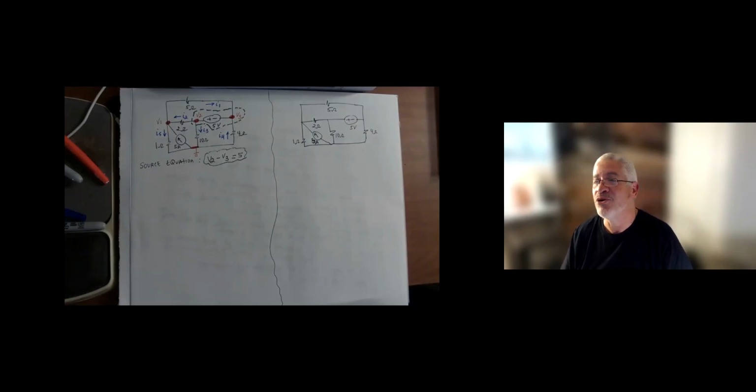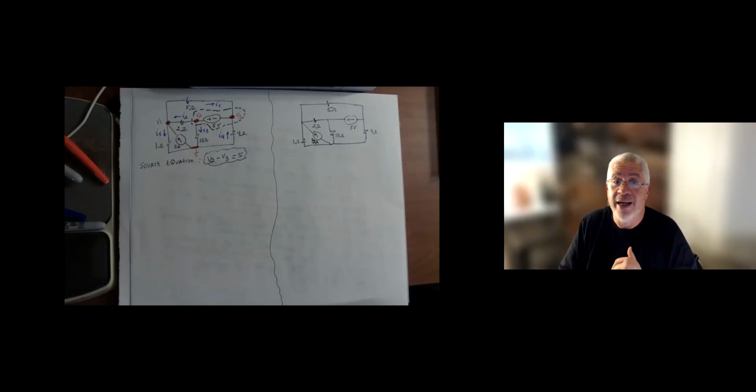And then I'm going to ask you, do we have a regular node? We do. It is node V1. That is a node that is not the reference node and is not connected to a voltage source. And this is the case where we will do a KCL about the supernode because the supernode does not have the reference node. So let me write the 2 KCL equations.